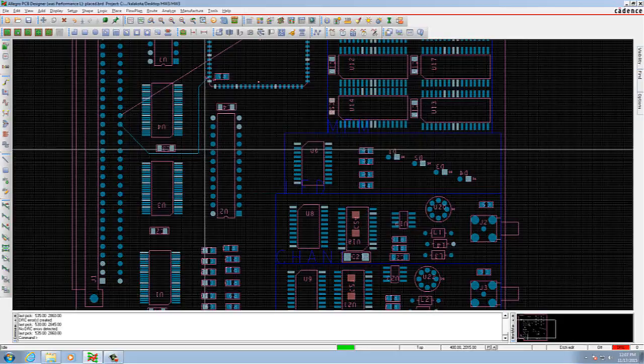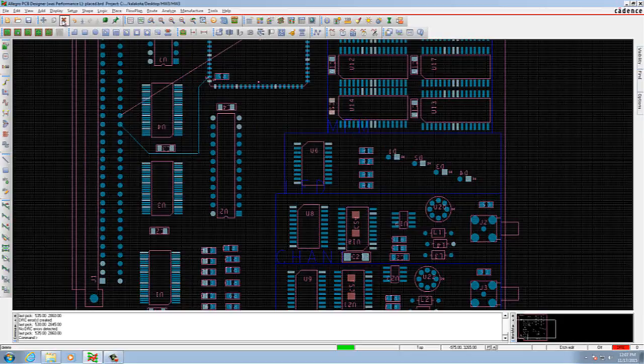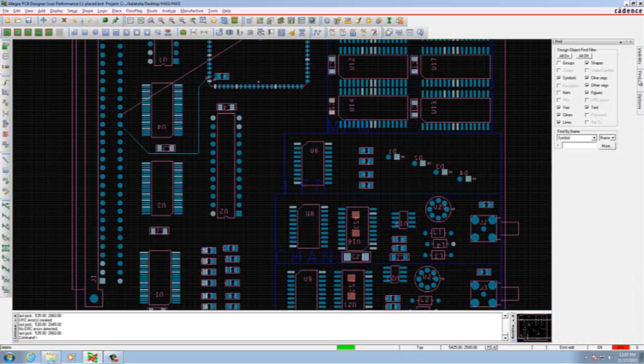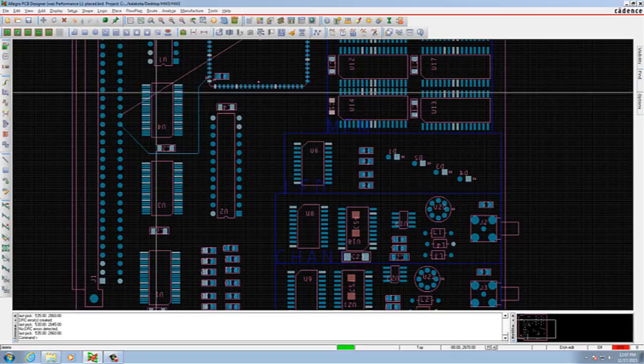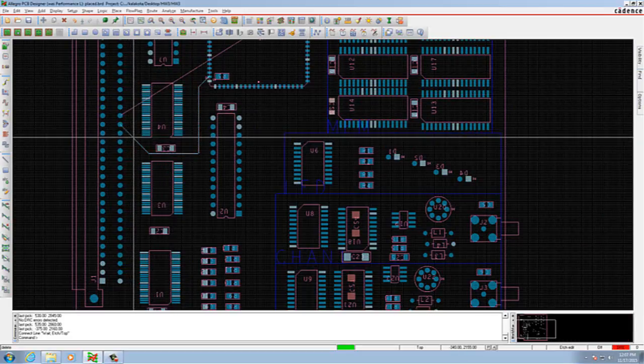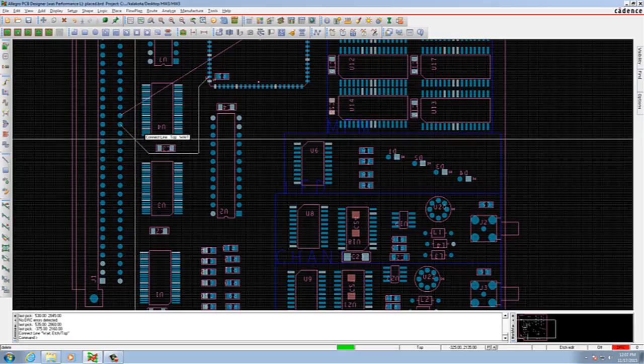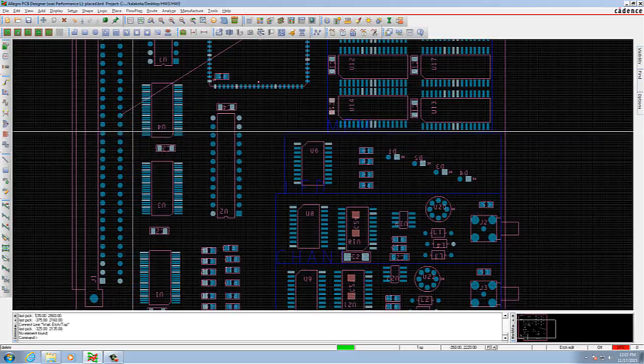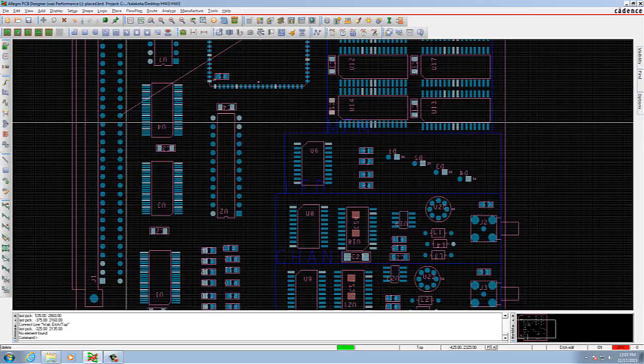Next we talk about deleting edge. So again we first click on delete on top, and then we go to the find tab, click all off button and check the C lines on. Click on MKCL net that we just created. So the line is now highlighted and it's gone, and you right click and select done.